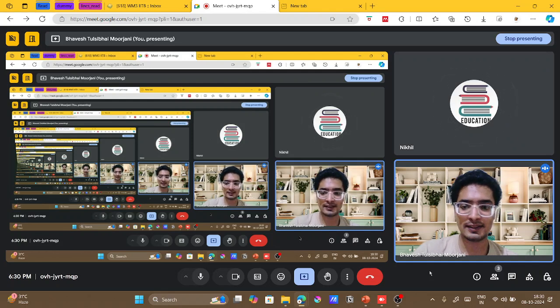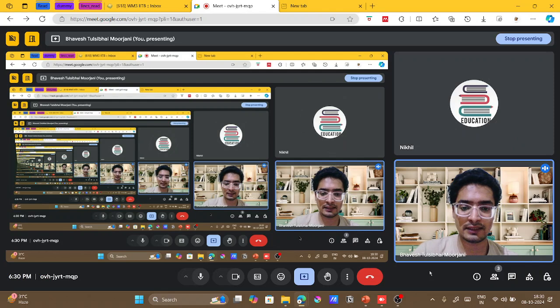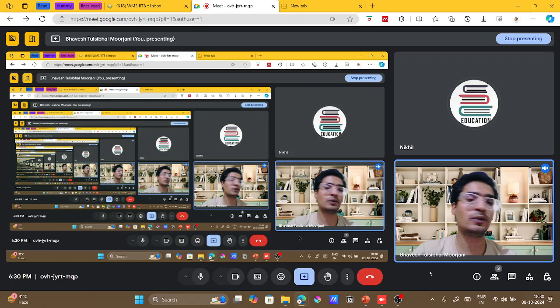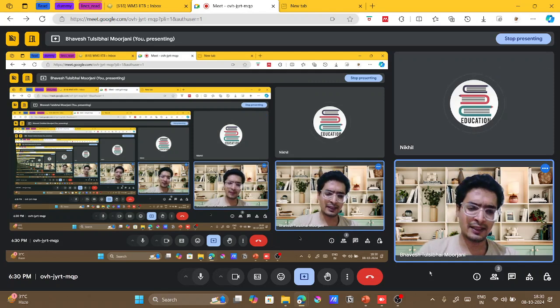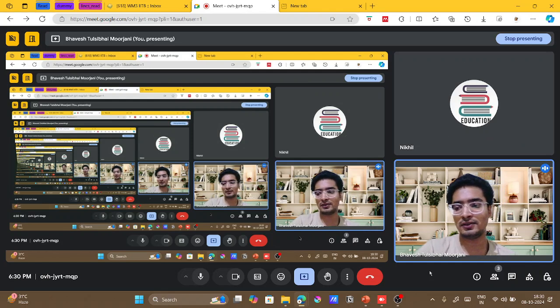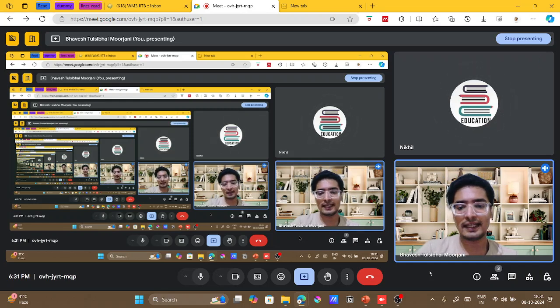So that could be the second reason, that separation cost will be too much, so there is no point of separating it. I think these two are the major reasons why inert is present. A third reason could be to control the heat of reaction. If your heat of reaction is high and inerts are present in your system, then they might absorb the heat, and your reactor is maintained at some optimum temperature. So there are multiple reasons why inert is there.